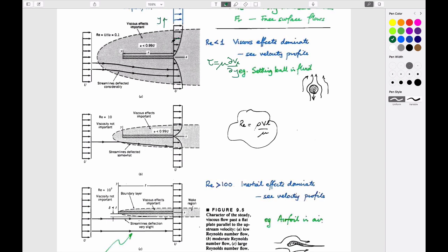If this gradient is slowly changing over a large length, that will give much more viscous resistance than if, as we go across this boundary, this changes very sharply from zero velocity, stuck here, to the far field velocity much closer in. This is a much steeper gradient, but if it happens over an infinitesimally small length, then the product of the gradient and the length over which it occurs is much smaller than this effect here.